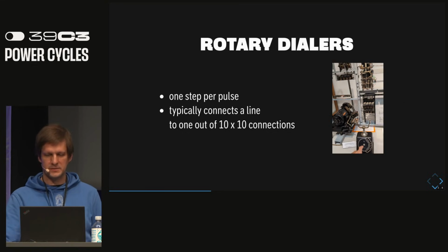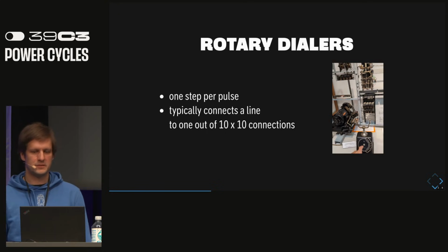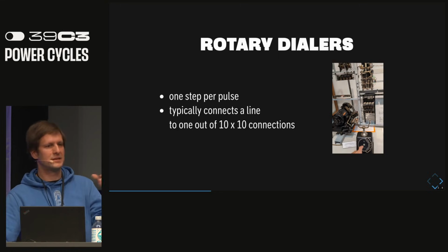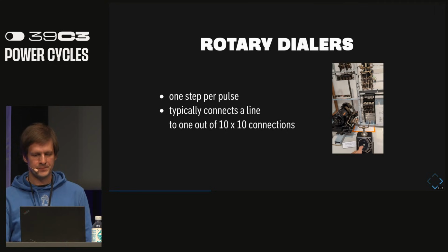And in newer systems, newer meaning from 1955 or so, System 55, they use a so-called EMD, Edelmetall-Motordrehwähler in German. So they have stepper motors inside, and they only move horizontally. First, they make 10-step increments, then 1-step increments.